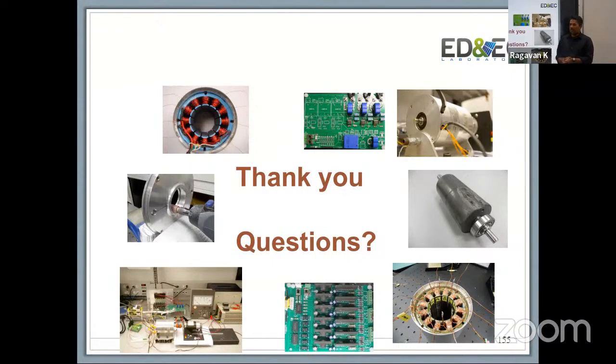Oh, without a doubt. Yes, it will reduce your motor life, but whether or not it's reversible is subject to how much damage was done. If you have a winding failure in the machine, you have to take it offline and redo the windings. That's not negotiable. But in terms of whether that causes a catastrophic failure beyond that, it shouldn't be as bad, because once you take out the copper, there's not much left in it, right?